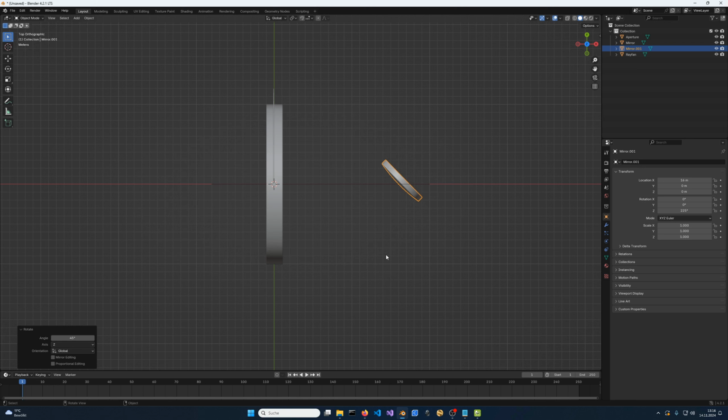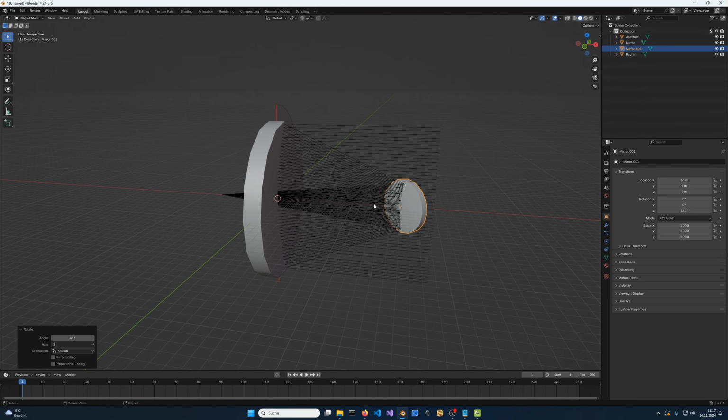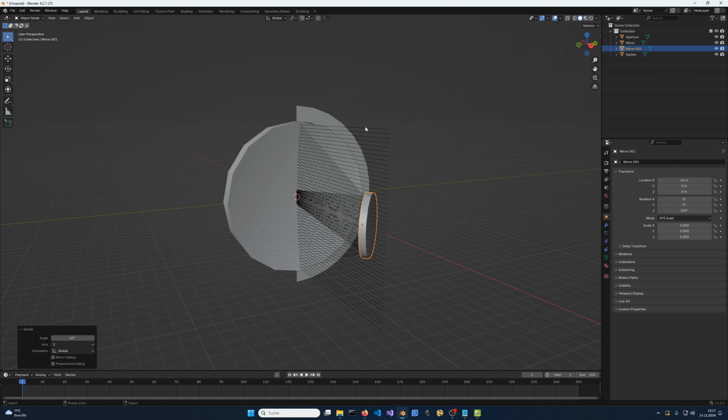And this is something that at the moment OptiCore does not yet handle, so be aware when you're trying to load this kind of lens system that the system may not be imported correctly. In case of a Newtonian system where the fold mirror is flat, that really wouldn't matter much. You'd get the focus position here, so not where it really should be, but still the ray tracing would work correctly and indicate a good focus spot size. However, there are also fully off-axis systems, so-called Schiefspiegler systems, where this would no longer work, because really you'd have to ray trace some off-axis segment of the mirror and not something revolved around the central optical axis. So in those cases, the optical design would really fail and it might not be obvious.